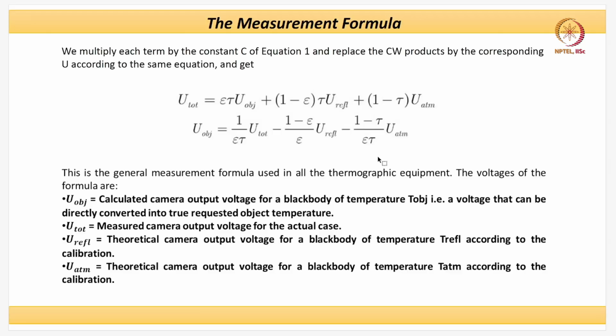But at the same time, because it registers a certain amount of radiation, the pixel resolution is not all that great compared to the normal CMOS cameras that you use for high-speed imaging. And the frame rate cannot be as high as high-speed cameras, so to say. So there is a certain amount of calculated risk always. There is a certain amount of error, especially if the ambient is very fluctuating. For example, if it is a hot day and it is showing buoyant plumes, so there is a plume that is going on.